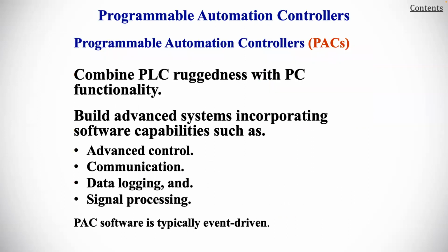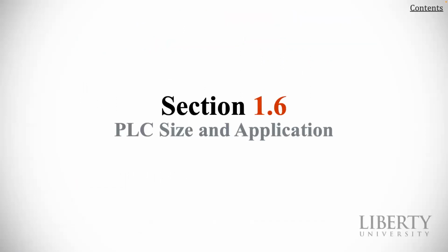So what about programmable automation controllers? Instead of PLCs, you have PACs. They combine PLC ruggedness with PC functionality. With this, you can build advanced systems incorporating software capabilities such as advanced control, communication, data logging, and signal processing. PAC software is typically event-driven.